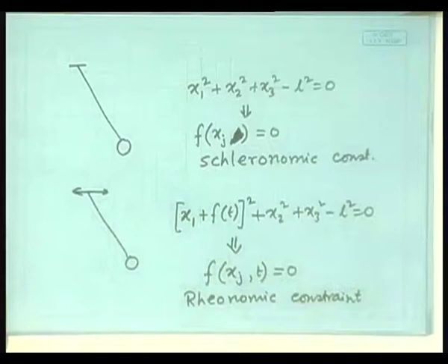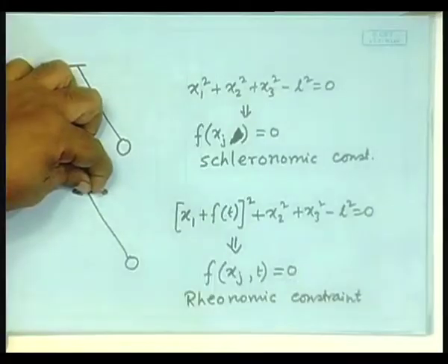Then that is the mathematical nicety that Lagrange thought of. He said that at any specific position of my point of suspension, this bob has some admissible motion. That means, if it is like this, it can only move in that direction which is orthogonal. That is the admissible motion, admissible displacement.